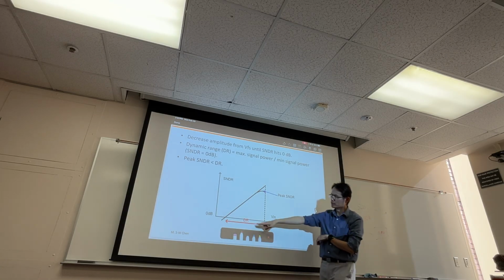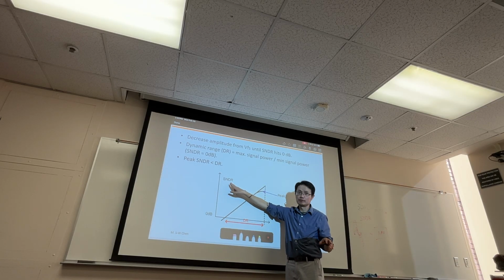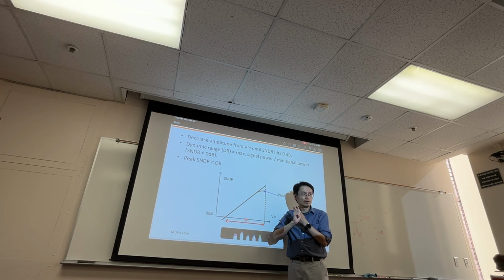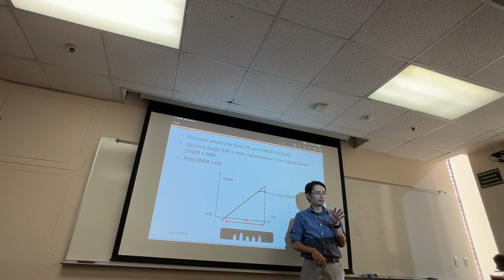In fact, at this point, you pretty much are talking about the noise. Why? I know SNDR means noise plus distortion, right? Why did I say that? When your input is so small, you are mostly just dominated by the noise.